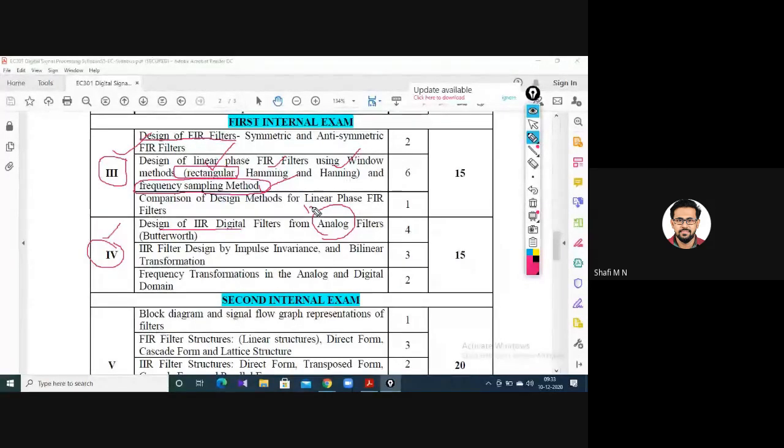So that was order. So after calculating the order, what was the next step? You have to choose the appropriate transfer function from the table. So you had a table for the first order, second order, third order, fourth order, and so on. That table is particularly applicable for low pass filters and with cutoff frequency 1 radian per second. So the next step is, after getting your H of s from the table, depending upon the order you selected,